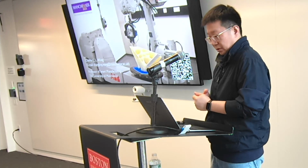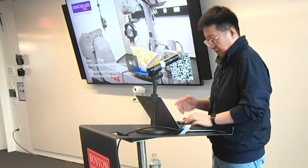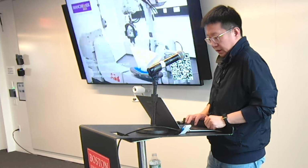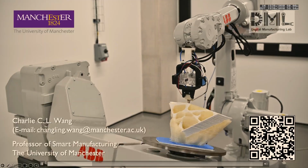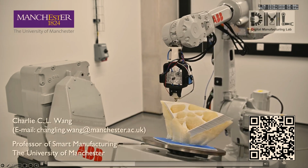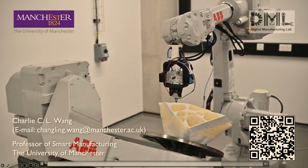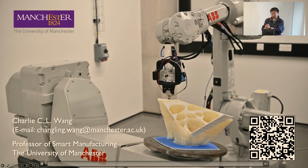Thanks for a very nice question. I should point out that is the most challenging part. At this moment, we have not really optimized or reduced the twist. One of the main reasons is that we're actually using a thin filament instead of a wide filament. A wide filament is used in an automatic fiber placement machine, which causes a lot of problems because it's roll based. So when you have a lot of twist, that makes many differences.